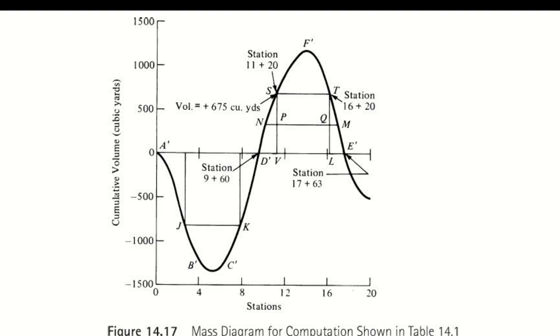This is the mid from 17 to 1763, and this is the material. Okay, so at 17 it is 303, at 1763 it is 0. So 303 minus 0. Okay, how much you got? 488. 488. Again, cubic yards, stations.